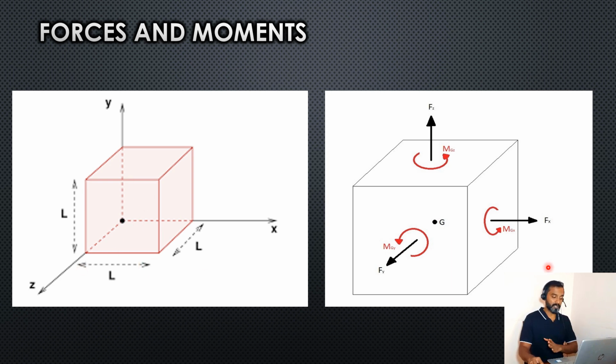So the forces and moments are equally important. You know why? Because the moment causes the twist. The more the twist, the more it will damage the piping, correct? Because twisting causes damage to the pipes. The pipe will get twisted and it will break as well. So the forces and moments both have to be within the limit. While we do stress analysis, we check whether the forces and moments are within the limit or not. That's where we have to understand the importance of forces and moments. These forces and moments are the results of the temperature, pressure, weight, and velocities, right? So this is how the concept actually works.